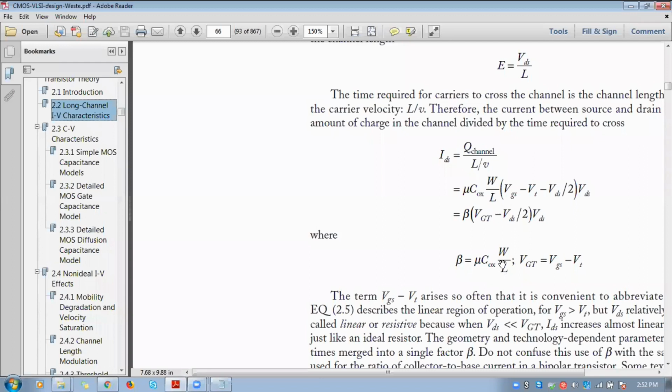But while designing itself, if the length of the channel is very, very small, it is inversely proportional to current. So if the length of the channel is less, current will be high. That is the geometric dependence case. That's why as nanometer technology progresses, as I explained initially, in the Intel 4004 we had 10 micrometer technology.